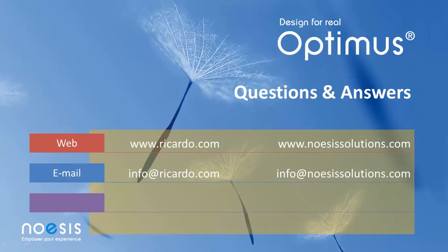Okay, let me proceed here with another question. Can you target both exhaust back pressure and acoustic SPL levels in the same workflow? Yes, absolutely. That's one of the key strengths of WAVE, and particularly using it within the Optimus environment. You can put exhaust back pressure over the entire system, or just an individual component as a constraint, and run WAVE at the same time to get the NVH sound pressure levels out. So that's certainly one of the advantages of tools such as WAVE that does engine performance and NVH coupled together, not just one or the other.